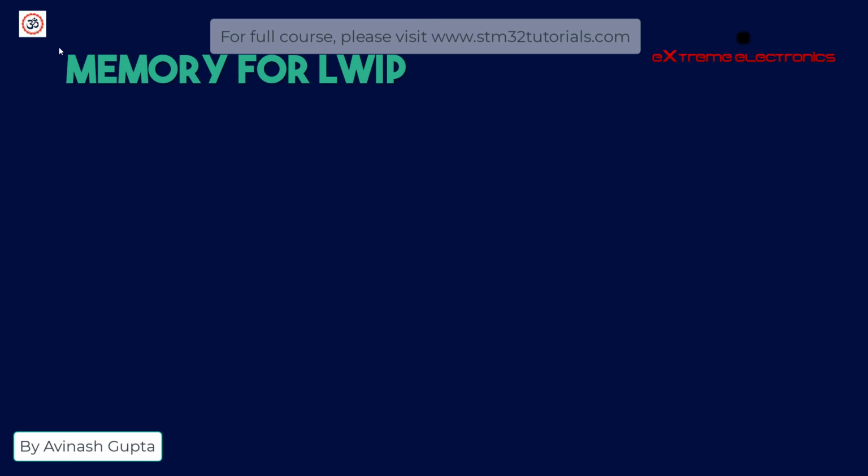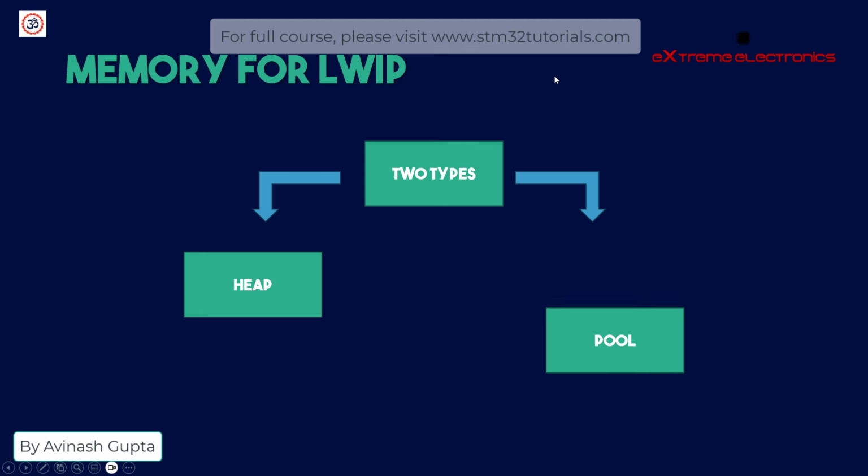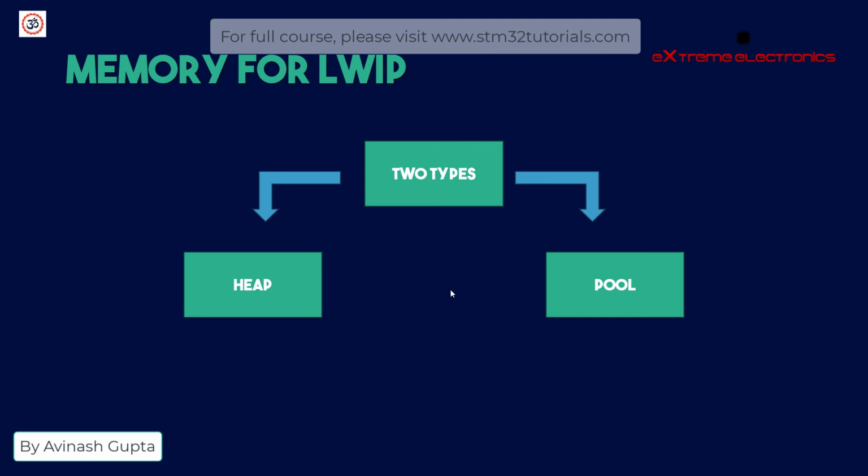So in lwIP's dynamic memory management system, mainly we have two types of memory. The first one is the heap memory and the second one is the pool memory. What is the basic difference between these two, heap and pool? You must already be familiar with heap memory. This is the normal type of dynamic memory that we can allocate using the malloc function, and since lwIP is designed to run on small embedded systems, it does not expect a memory manager to already be present in the system. That is why it provides its own customized dynamic memory manager.